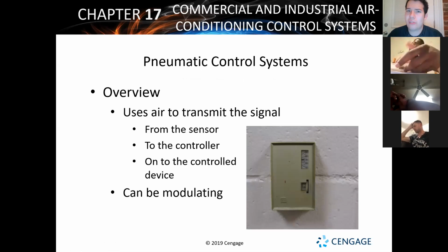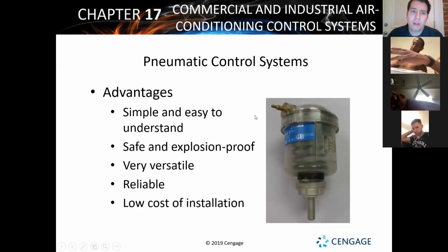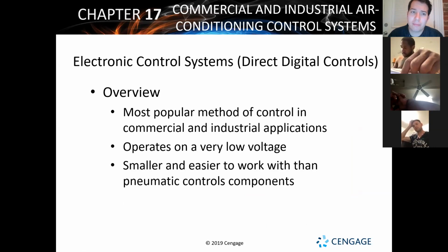Instead of an electronic signal, it uses air pressure to send a signal to turn on and off thermostats, fan motors, everything like that. To operate relays, it's all going to be off air pressure. Again, more things that are nice about pneumatic control: it's explosion proof, easy to set up, and very, very low cost as far as maintenance and running it and everything.